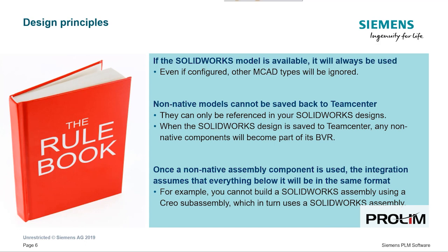Finally, nested reuse cannot be supported. Non-native assemblies of any depth may be inserted into SolidWorks parent assemblies, but they themselves must not contain any non-native children.